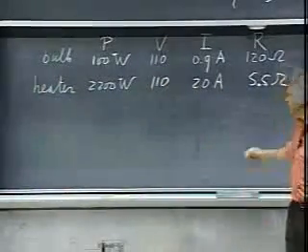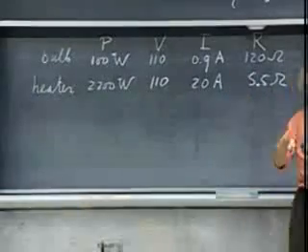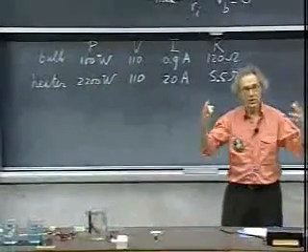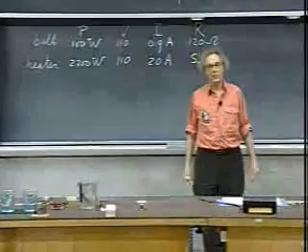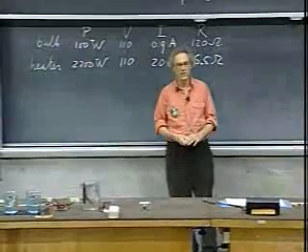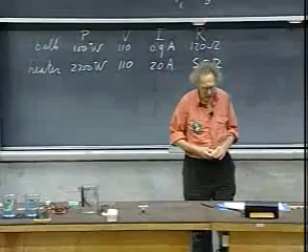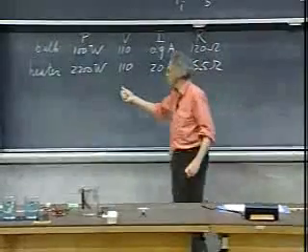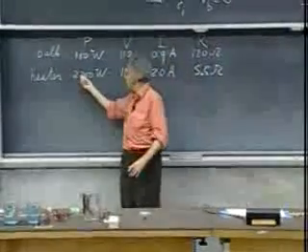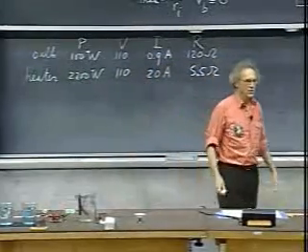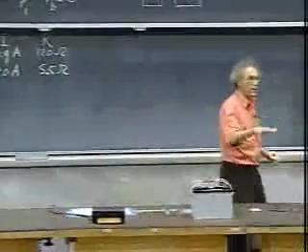Now you want heat out of your heater and you want light out of your light bulb. So you want to keep the temperature of your heater modest, not so high that you get a lot of light. If you make it 2000 or 2500 degrees, then you would get a lot of light out of your heater. And so suppose that half of that power would come out in terms of light, and you turn on your heater at night, it would be like having a 1000-watt light bulb in your dormitory. You don't want that. So what do you do? Well, you simply keep the temperature about maybe 1000 degrees centigrade. It gets a little red hot. Very little light is produced.